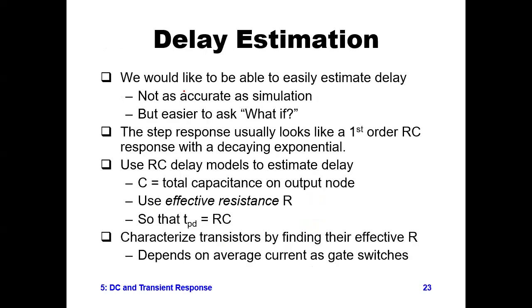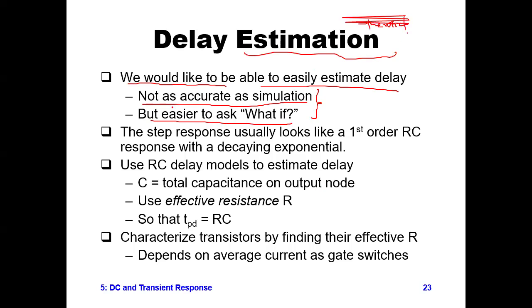What is delay estimation? We would like to be able to easily estimate the delay, not as accurately as simulation. They are talking about the theoretical estimation. The step response usually looks like a first order RC response. There is a case where they show the MOSFET as an RC circuit. In the next lecture I will also tell you how the MOSFET can be taken as an RC circuit.